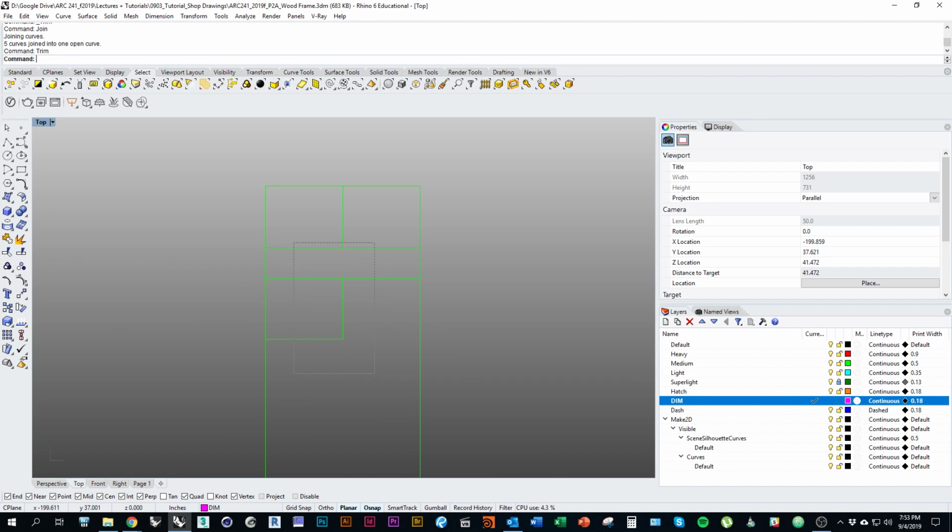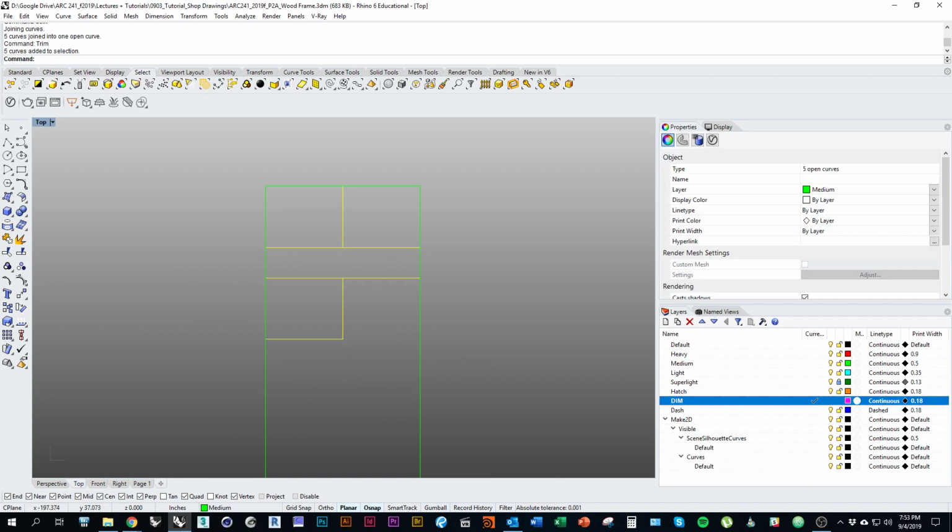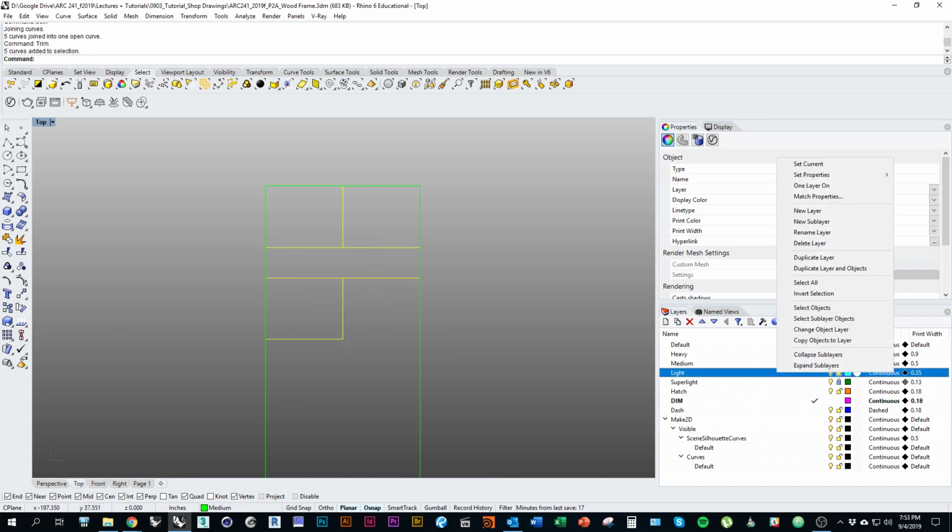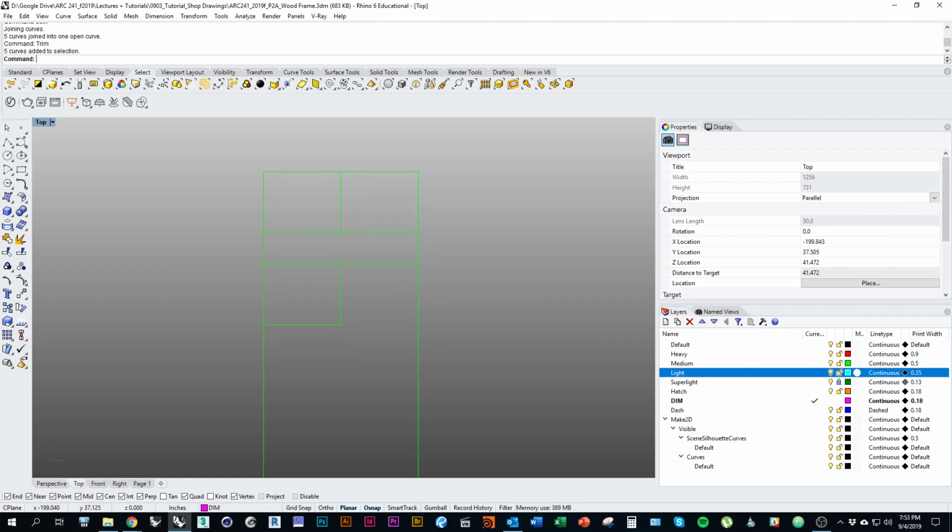So again, in here, I would also, real quick, change these interior lines. Or I'm sorry, no. What I want to do is just type in hatch. So use the command hatch. Make sure when you type this in, you have nothing selected. That way, when you go to hatch it, you can choose this option boundary. So I'll click on boundary. And then I want to click and drag and select all my lines, including my little cutoff line. Press enter.